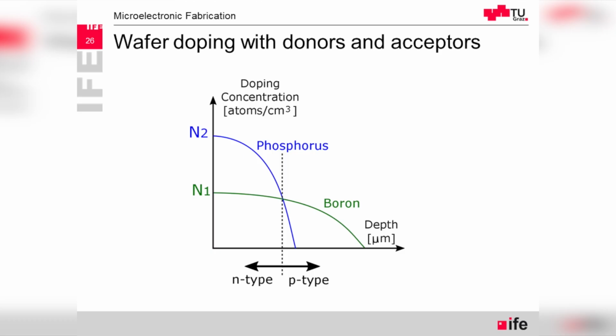What is important to also remember is that until now we had process steps that are high temperature. There will be the topic of temperature budget. Every next step can only be at lower and lower temperature, because if we later have a high temperature process step, it might destroy, put out of control everything that we have done so far. Diffusion and ion implantation are high temperature processes.